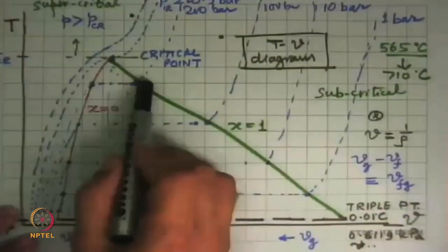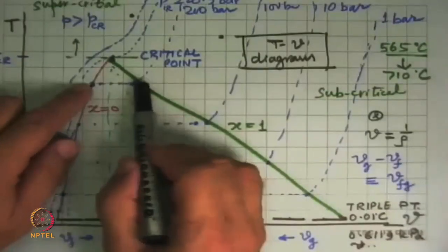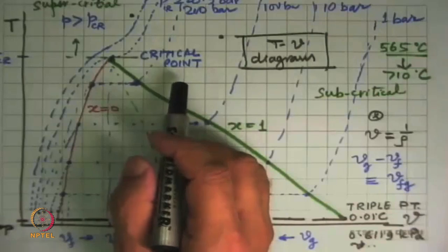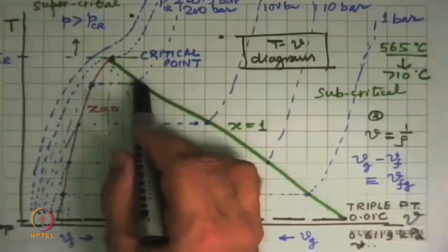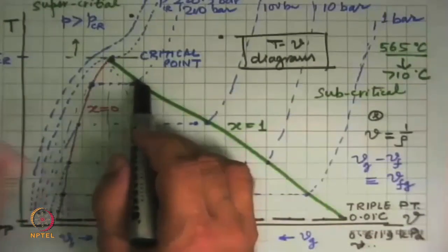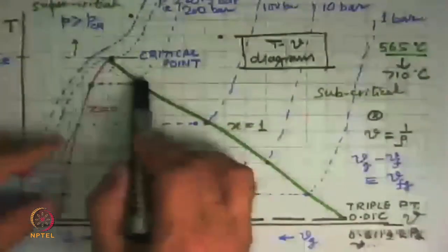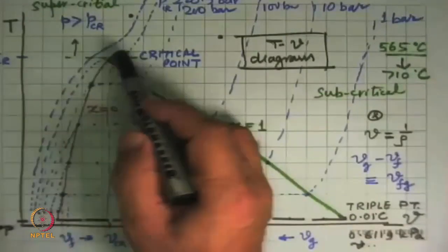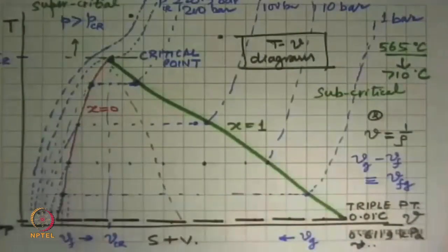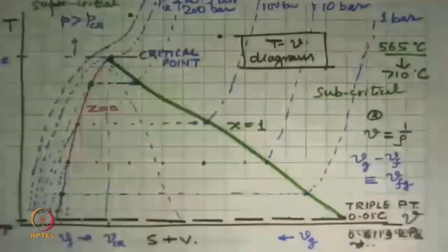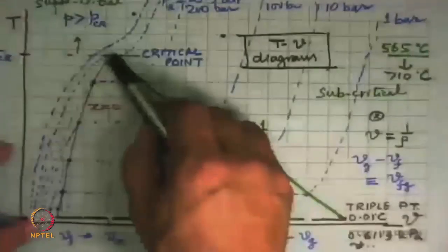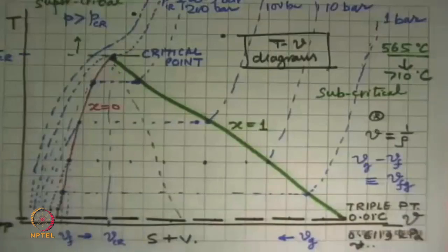So you saw here, below the critical pressure at any point, there was a distinct thing which is called a liquid, where the intermolecular spacing was something. It became a vapor where the intermolecular spacing suddenly increased. This does not happen at the critical point because you have increased the pressure so much that this inhomogeneity that we saw has disappeared. It continuously shows a behavior of one type only, where the intermolecular spacing is now fairly tight and very close, and it doesn't show any ability to become a vapor by getting the molecules very far apart. So that's why this happens here. And of course, if pressures are more than the critical pressure, there is absolutely no hope, because now you have compressed it so much, molecules are so close to one another, they have no chance to get away from each other.